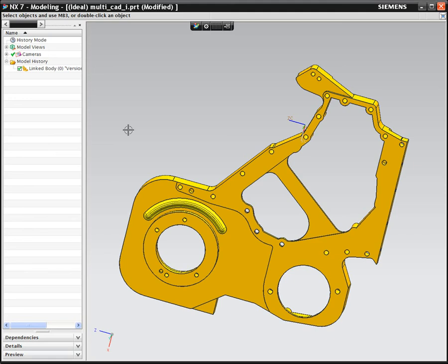Next, you will perform a series of 4 design changes using synchronous technology commands. The purpose of these commands is to simplify the geometry and make it suitable for meshing. First, use the Make Coplanar command to remove a small lip in the model.